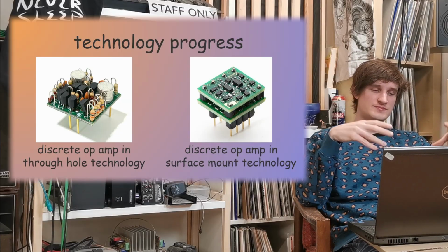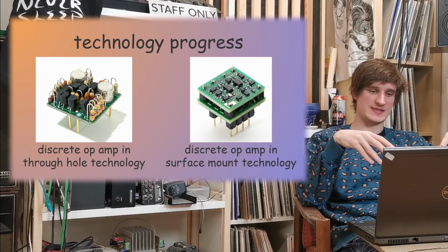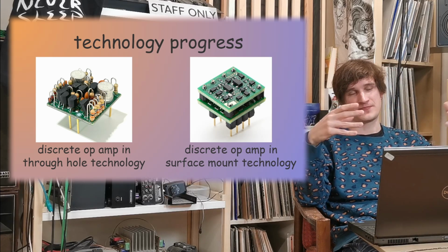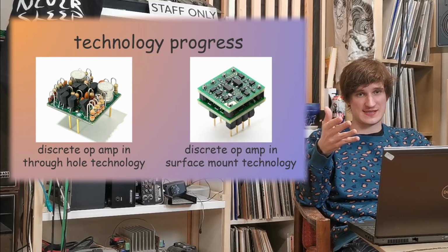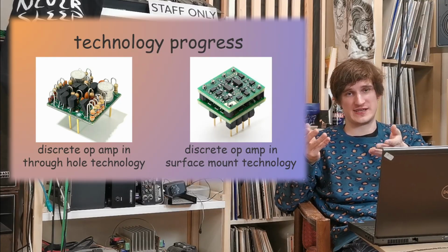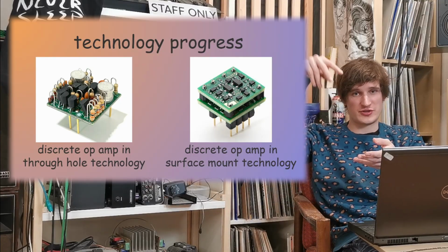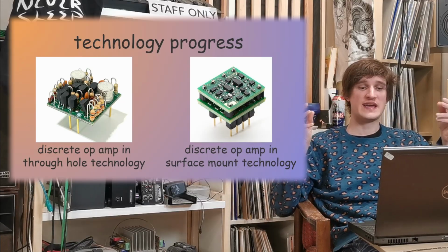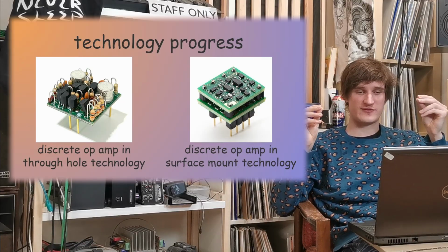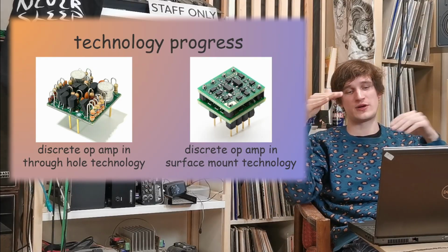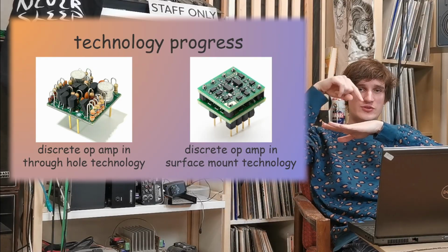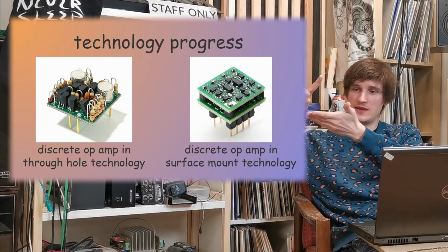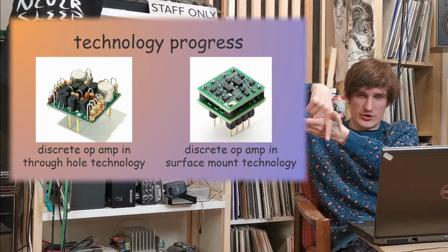And the truth is that the SMD components are the same solutions, but the way of mounting is just different. They are not through-hole, they are mounted on the surface, and also the size of components is different, because when you mount something on the surface, you don't have to have large leads to carry them through the board.